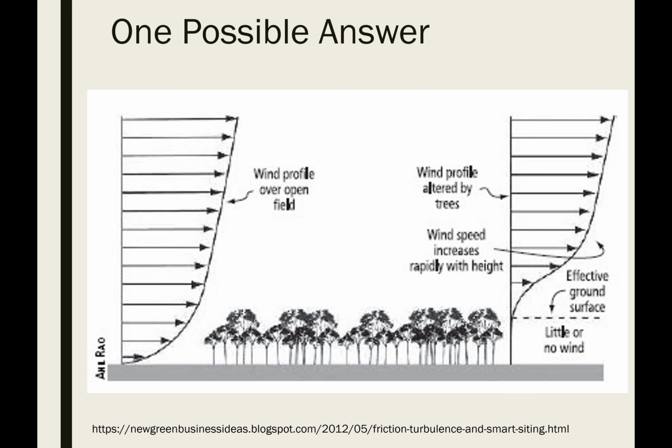So while all of your answers were valid and probably really smart reasons, this is another reason that the wind speed is actually reduced. When air or water flows over a surface, there is a drag force between that very bottom layer of the fluid up against the solid, and so you actually get lower velocities closer to the solid. And then the higher up you go, the faster and faster that velocity gets. So it's really a conceptual way to motivate you into thinking about boundary layers.